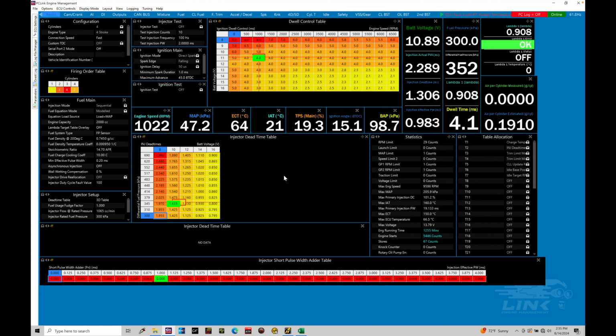Now, in addition to understanding how to program the limiter, that's pretty easy. There are advanced cut strategies here in the software that I want to dig into and model with the engine simulator so you can see how they actually work, because it's easy to get lost in some of the settings. If you can see things slowed down, you can decide how you want that limiter to be placed on the engine that you're calibrating and tuning, and it gives you a lot more control rather than using the default limiter settings that they have in place. So you may want to experiment with doing some advanced setup. We're going to take a look at that.